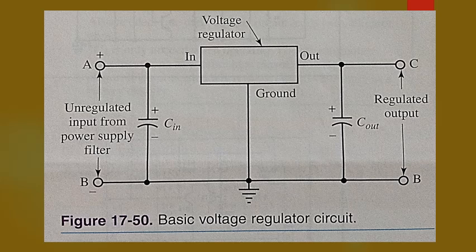Regulators come in a number of common transistor package designs: TO3, TO39, TO202, TO220, etc. The solid-state regulators are basically blowout proof. They require that a heatsink be used to remove excess heat from the device.